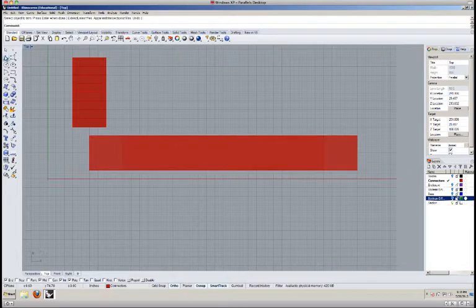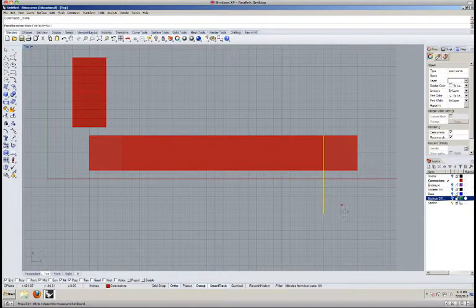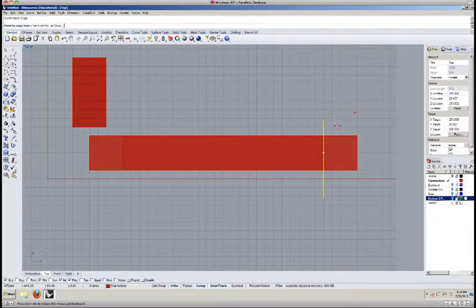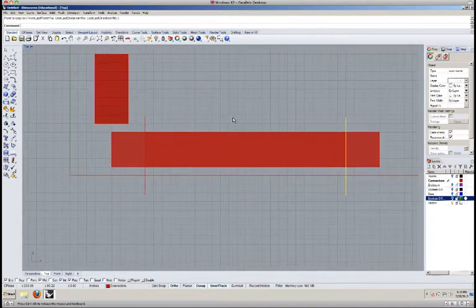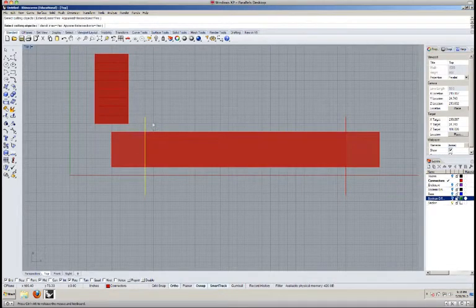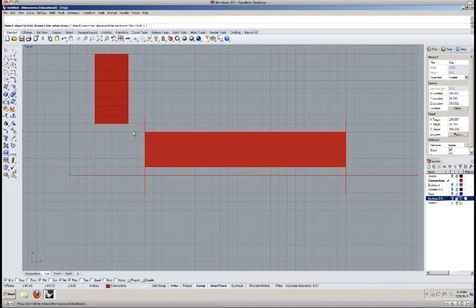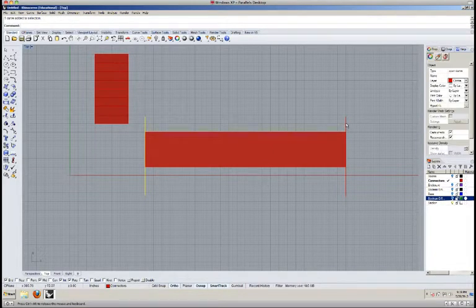If not, I'm going to use the polyline command and use this as a reference. Just drawing a line based off of those points and then copying it over from this point over to this point. And the points I'm referring to are the ends of the ramp that I can see ghosted through the top plane that's too long. So then I can use these lines to project. So trim. These are the cutting objects, enter, and I can just delete the sides of these. Enter. And get rid of these so they're not in my way.